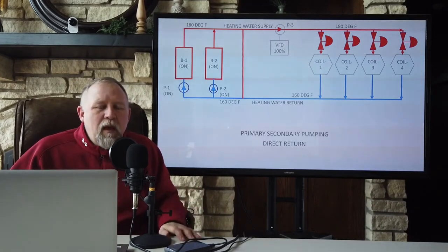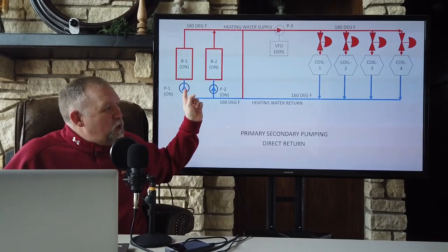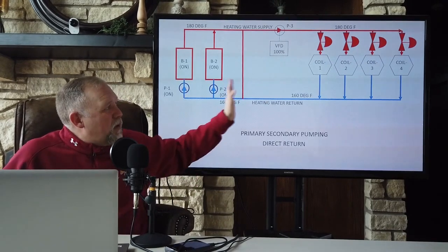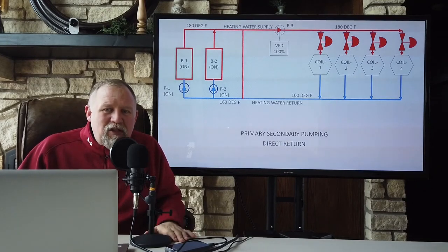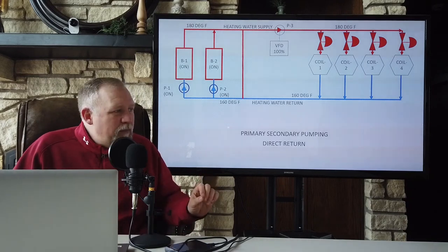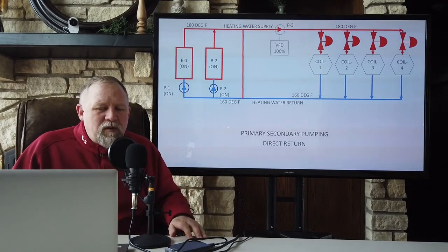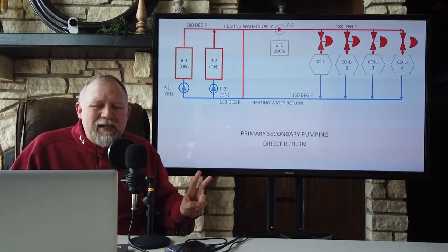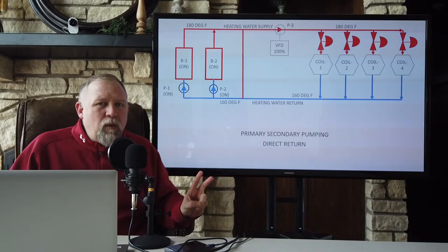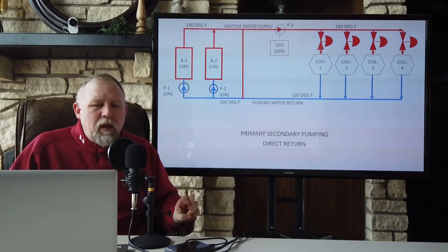you're picking. But I've used as many as 9 2 million BTU per hour boilers in a row for a very, very large building. And the advantage is this. This lets us use these high efficiency boilers with lots of redundant backup. In other words, we can lose one for maintenance, or we can lose one for a breakdown that needs repair, and we don't significantly cripple our boiler plant.